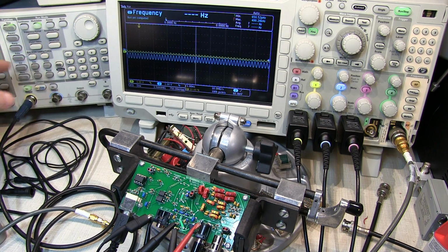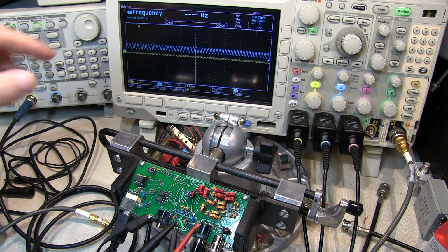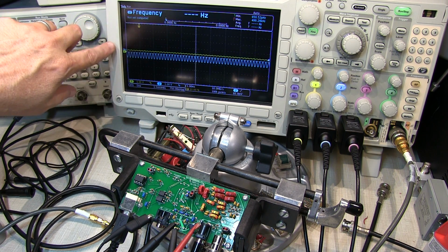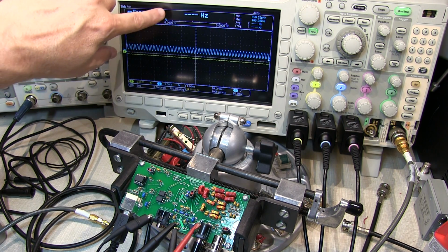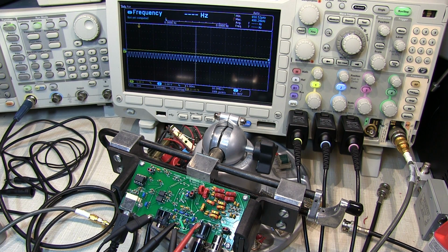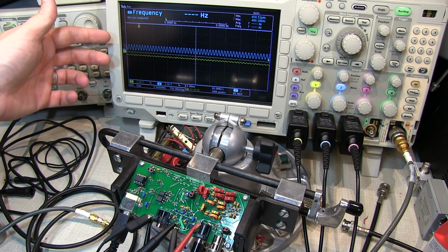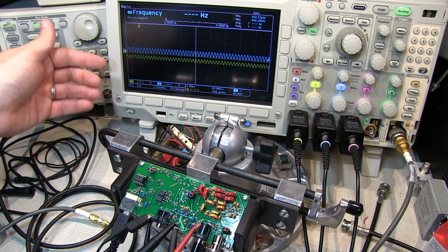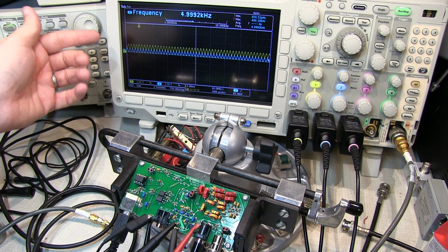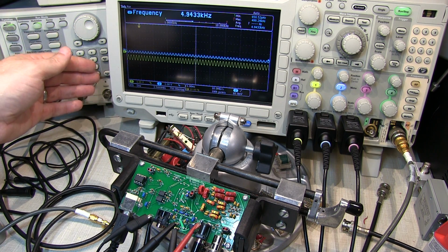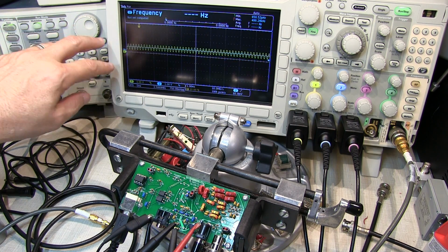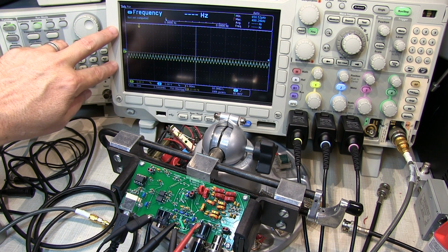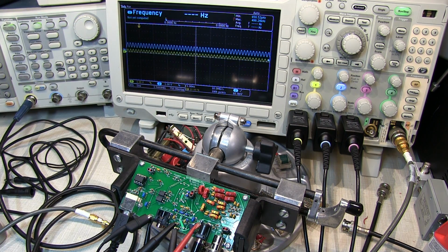This is a 5 kilohertz modulated tone, and we can see every once in a while when I get enough amplitude on channel 2 that I'm reading about 5 kilohertz there. Now with the I and the Q signals, if you're actually going to measure amplitude, you'd have to combine the two of them in an RMS fashion, the square root of I squared plus Q squared, and the amplitude in that case would be constant, and we would see just the 5 kilohertz modulation.